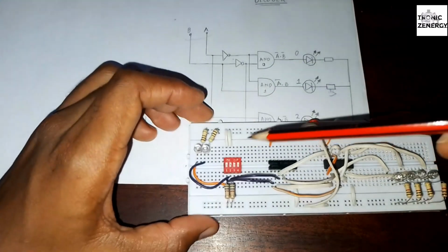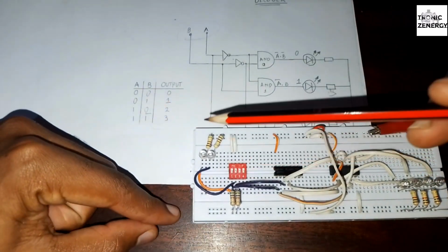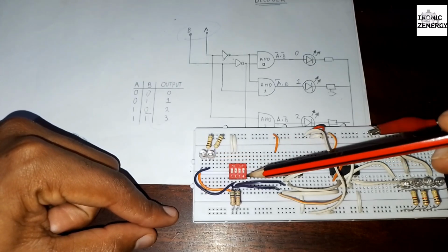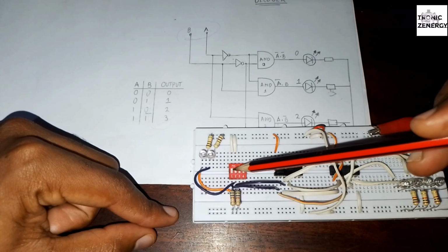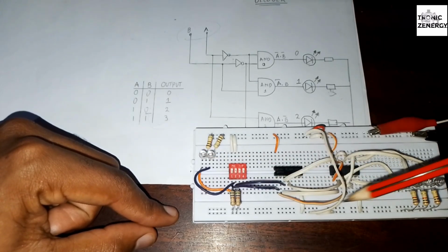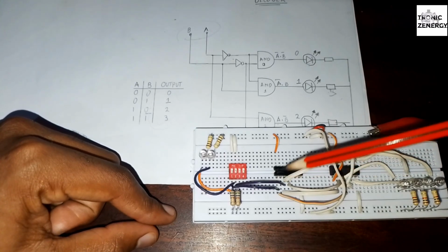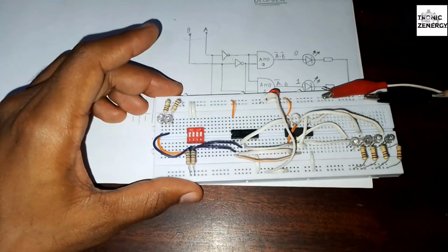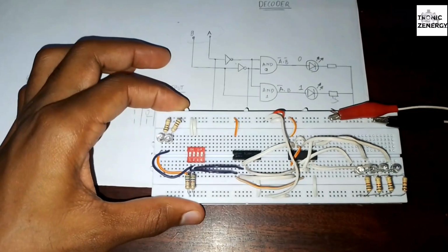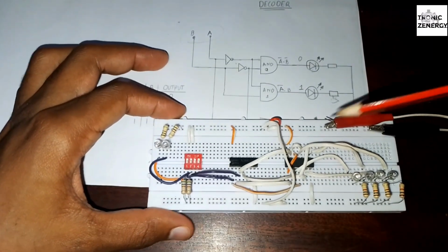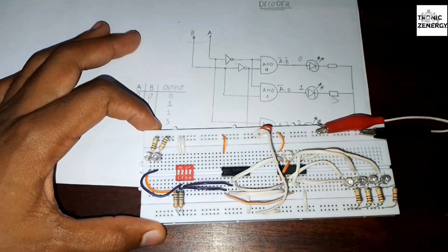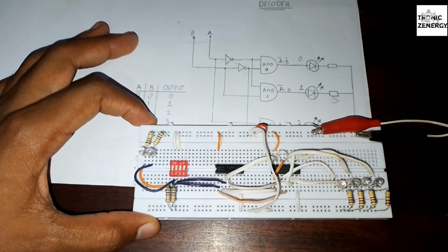And my control or my input section is right here, containing A and B, which are orange LEDs, and I'm using the dip switch, those two switches, to control which input I want to set. So that's basically what the circuit entails. And I'm using a 5-volt power supply. You can use any from 3 volts, but make sure you check the ratings of your integrated circuits to make sure that you don't damage them.